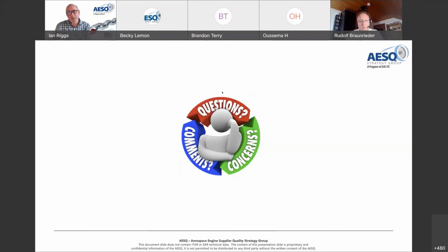If a customer says to you, but these 5 characteristics are absolutely key because of safety concerns, the purpose of that is when you do your FMEA, you're expecting to see that flowed into how you do the scoring. So for instance, the severity score you'd expect to see reflected because it's a key characteristic. The occurrence score, you're going to look at, well, if it's a key characteristic, should I be mistake proofing this? How critical for safety is it? In many cases, a customer might have a different level of capability for a key characteristic to non-key characteristics, so it might be a CPK of 2, whereas everything else is a CPK 1.33.